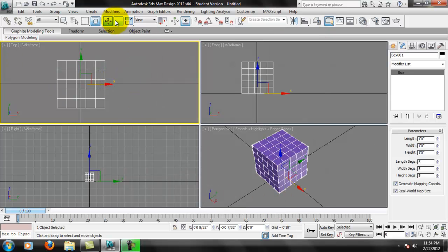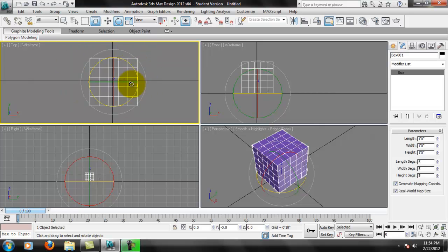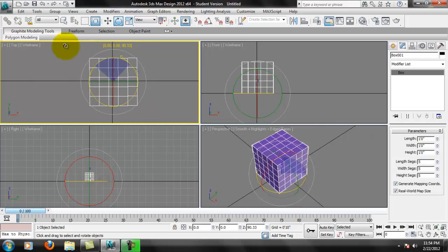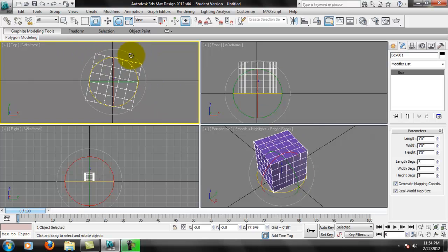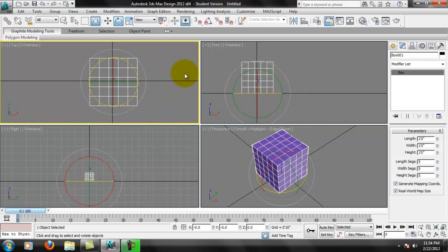Alright, so jump over to the rotate. Now the rotate has a different gizmo. The rotate has the circles, and it's basically as simple as selecting the circle that you want to rotate. When you're in a top view like this, I'm going to undo that back 2 steps, there really isn't much to it.